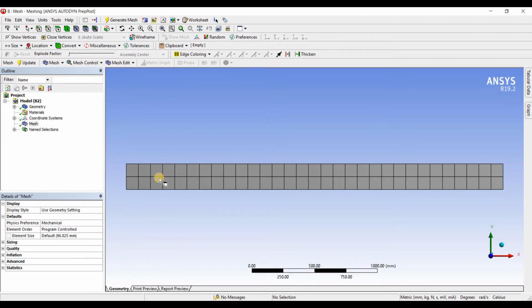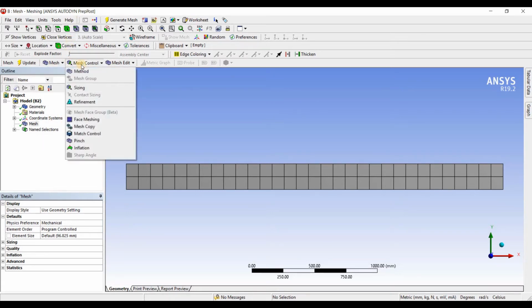As I mentioned, the accuracy of the CFD solution is governed by the number of cells in a grid. By seeing this mesh, we can't really say our CFD solution is more accurate. So firstly, to increase your number of elements, you need to know what mesh controls you will have.